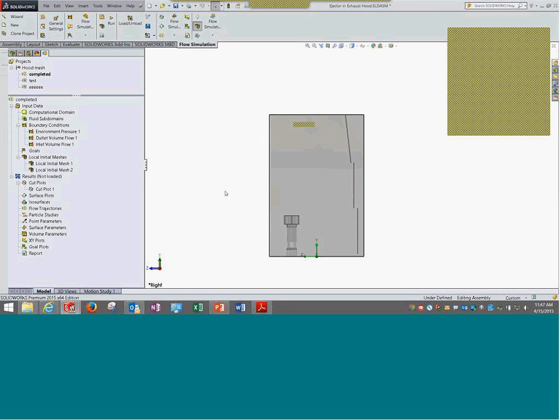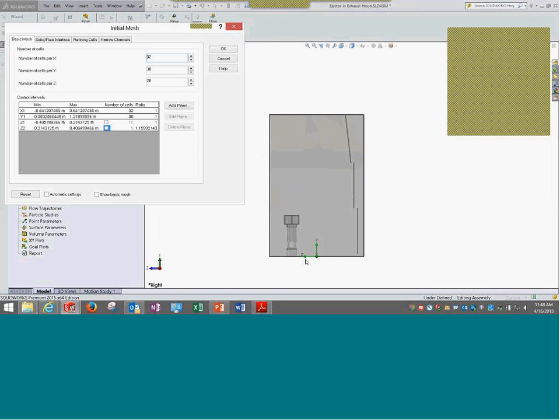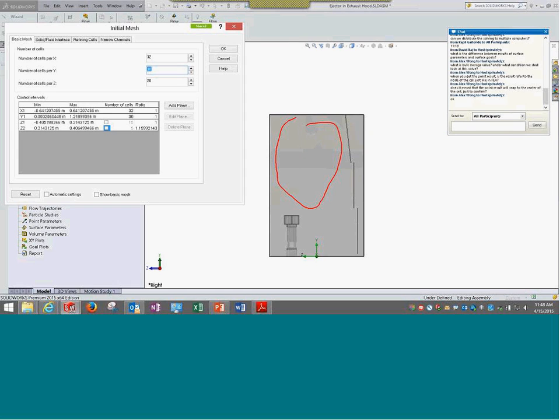First, finish the discussion. See here, the numbers we are specifying now. For example, if I take this Z direction, which is along this thickness, I'm saying I have 32 elements, and along the visible direction I am saying I have 30 elements. I am fine with a coarse mesh along the 30 because most of the area is blank here, nothing around here, so it is fine to have coarse. I need refined mesh only here, along here somewhere, right? This is the kind of mesh that I can control from here.